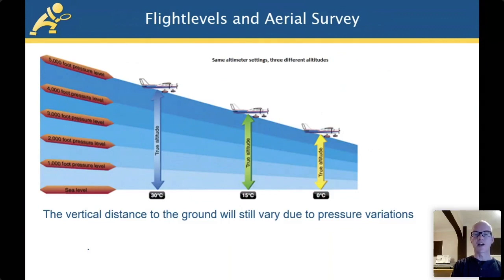Now the variations of the height to ground is crucial. So the higher you are, you actually get a little bit more overlap, but you get slightly less resolution, which is usually fine, because the critical thing in all of our surveys, you want to maintain that overlap for the accuracy of the data.